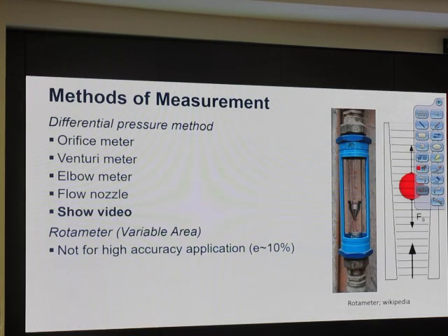All right? When we have gas, Coriolis flow meter measures very accurately. But if we have too much gas, like he said, there's a separation between the center of gravity of the fluid and the center of gravity of the pipe. So when they are not in the same location, the calculation that shows the answer will be somewhat wrong. Okay? So you can compensate for that by buying a low frequency or buying a bigger unit.